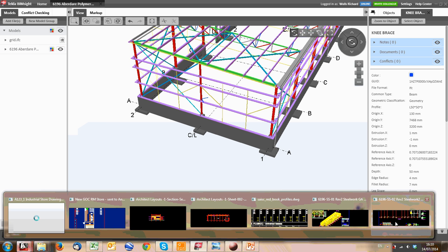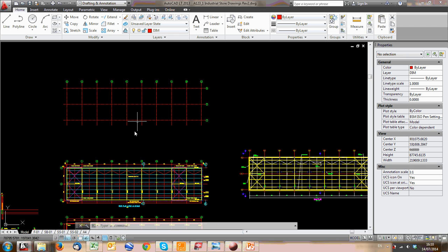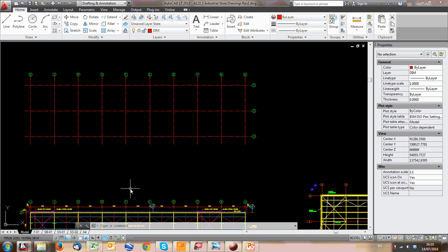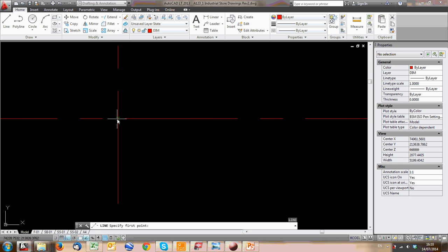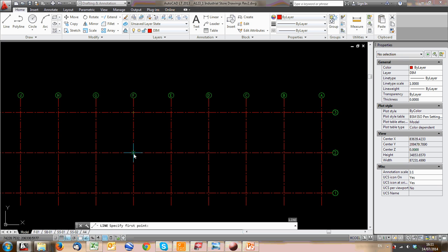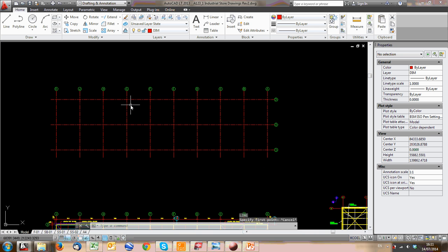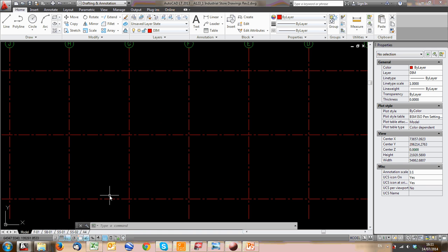Okay, going back now. Now that we've done all of that, we can set out a grid. You've seen as I've been going, there's been a lot of things happening with these little tools where if I try to draw a line, for instance, it snaps. You'll see that there's a cross that pops up there, or a triangle, all these various things. These are the snap tools. They're down the bottom here. Snaps are extremely useful because then it will sort of zoom your pointer or track your pointer to the nearest of certain types of points.